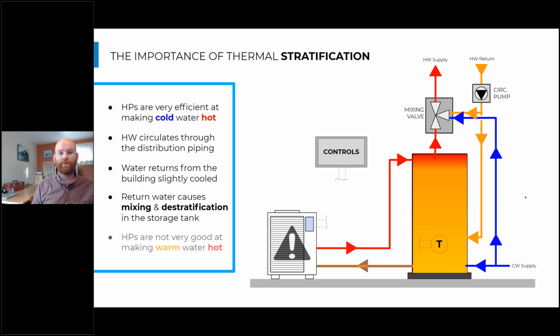So when that single pass heat pump water heater turns on, we start to pull in water that may be at 110 degrees Fahrenheit. So it's already heated most of the way, and we're trying to finish heating it or put more heat into it. Because it's already hot and we're trying to dump heat into it, that can be a very challenging operational point for that heat pump water heater, and it may result in issues. The other thing to consider here is how this system was sized.